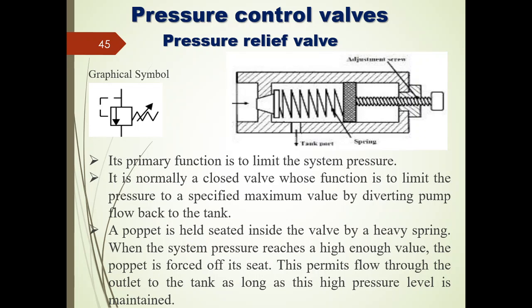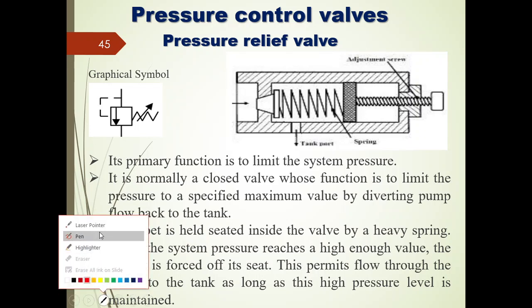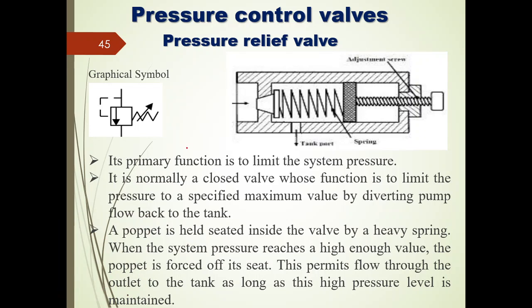The first one we will discuss is the pressure relief valve, which is an important component, an important valve, in case of all the hydraulic systems. Right? Whenever we go for using the positive displacement pumps, then compulsorily we should use this type of pressure relief valve. By the use of this pressure relief valve, the system can be safeguarded. So this is compulsory whenever we go for the positive displacement type of pump.